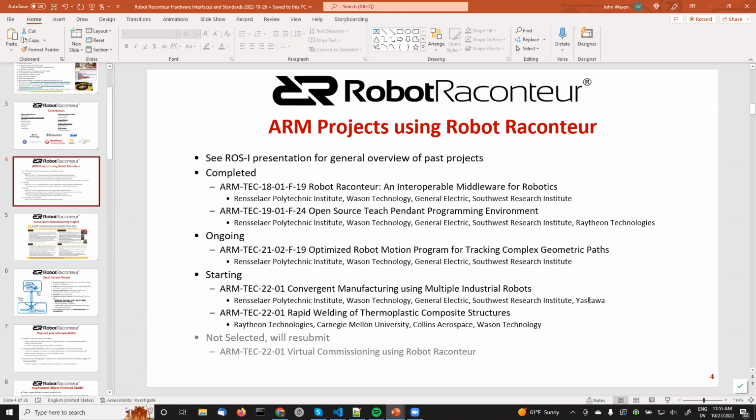Not all OEM simulation software is equivalent, right, as far as actually representing the behavior of their robot controller. And MotoSim is notoriously limited. Robot Studio is really pretty impressive how accurately, quote unquote, accurately it represents the robot. There are, of course, differences in performance compared to the real robot, but they do run the full controller on your PC. And that's been really exceptional for developing these drivers, because you can test everything out and catch most of the bugs in simulation before you put it on the robot.